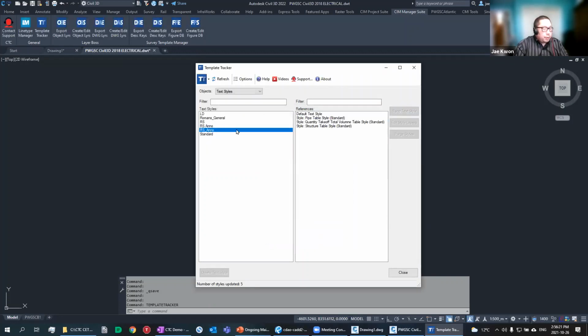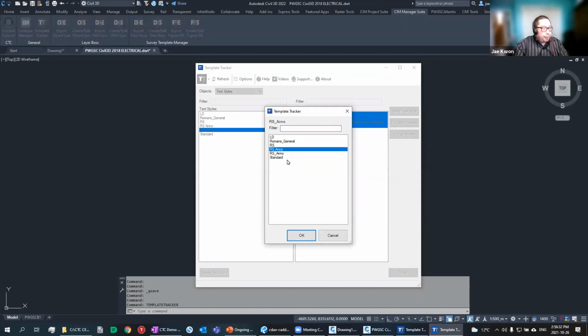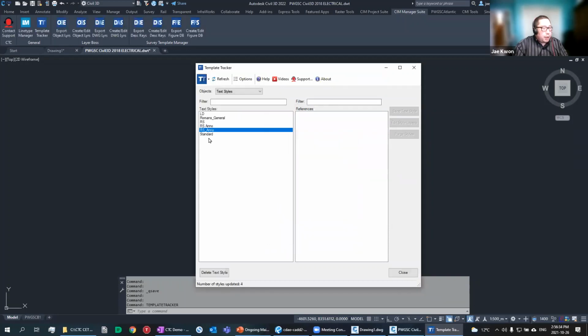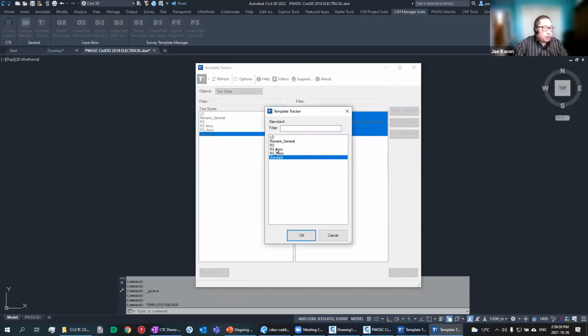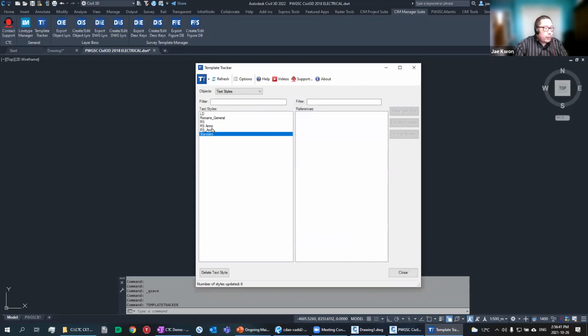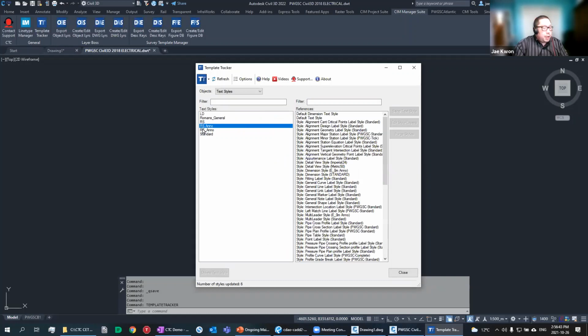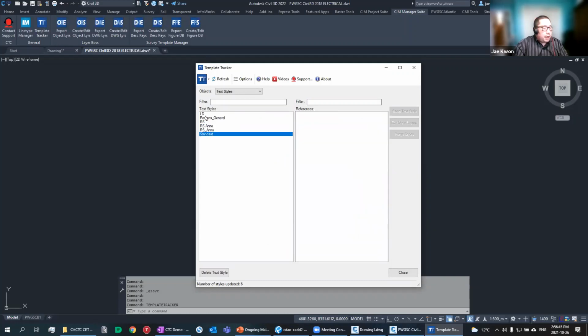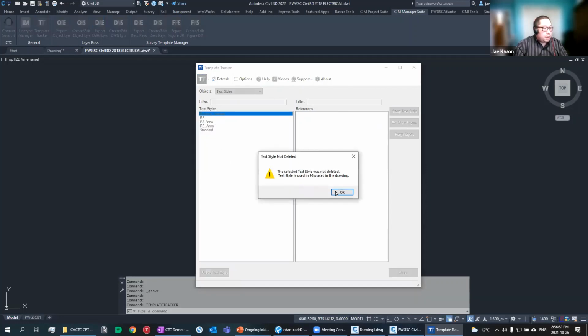And this one's some kind of a duplicate. So select that text style. I get a list of all the different styles that are using that text style. So swap it out to RSNO and standard. Same thing here. Swap that to here. Okay, so everything should be in this text style. Now I can get rid of the other ones. I'll just delete that one, that one.